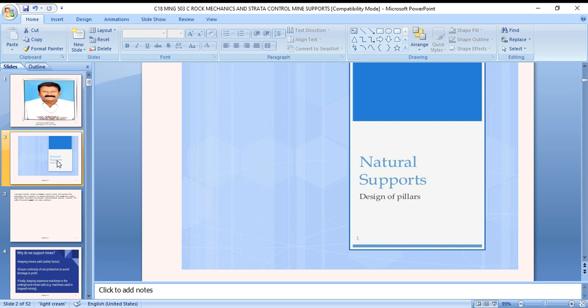In general, as per the principles of supports requirement, based on the rocks available in the coal mining area: sandstone, shale, clay, and coal seams. Before excavation is done in an underground mine, the rock is in situ, subject to vertical and lateral pressures, which as we well know are in equilibrium in nature.